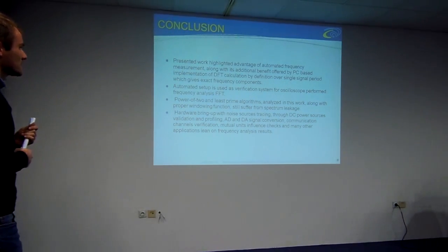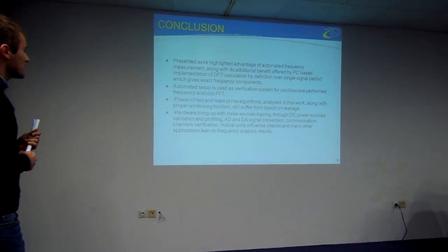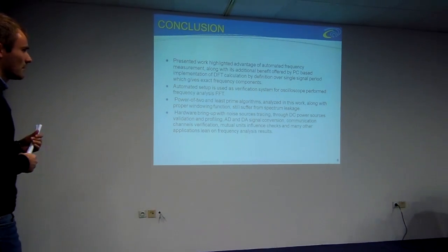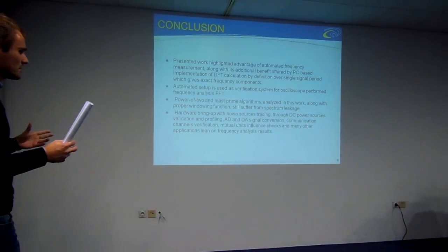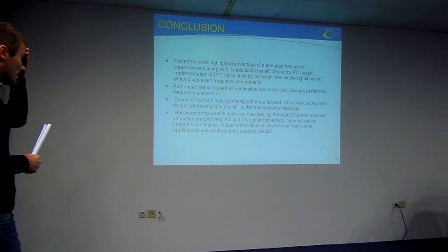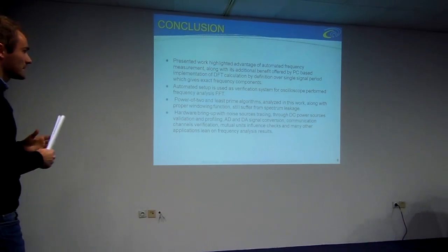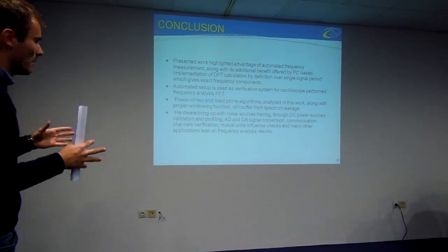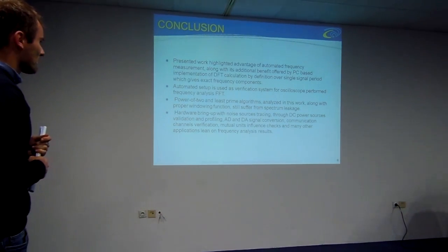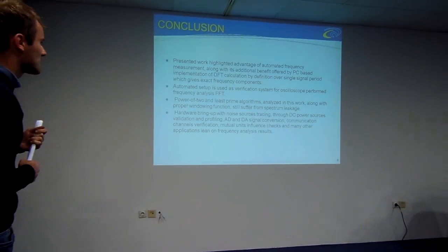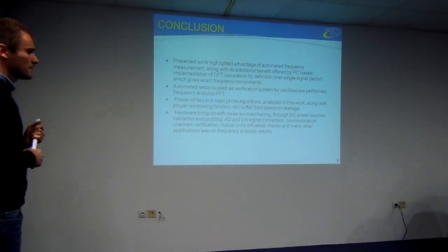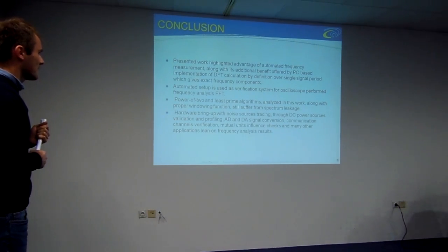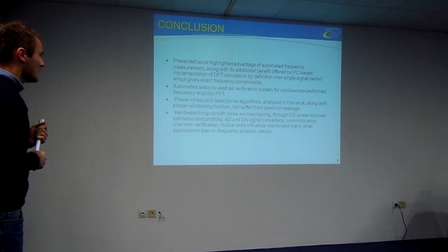This work highlights the advantage of automated frequency measurements, along with the additional benefits offered by the PC-based implementation of DFT calculation by definition over a single signal period, which gives exact frequency components. This automated system is a verification system for the oscilloscope's FFT frequency analysis.